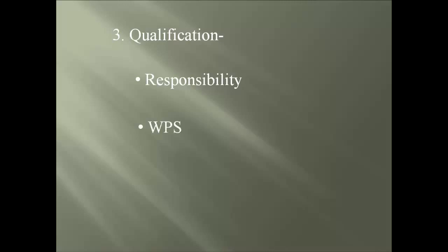As we just saw, the contractor is responsible for the establishment and approval of the WPS. The WPS for the reinforcing steel follows the same recipe as both the plate and sheet steel requirements, but there are a few special alerts to be aware of. First, the largest bar used within production welding will establish the WPS. Next, the highest carbon equivalent for the bar will establish the WPS.